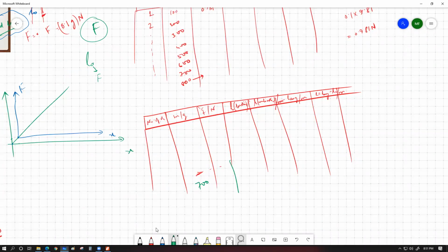So 700 gram is going to have one length value for the loading case and one value for the unloading case. Now you might wonder, within the elastic limit, these two lengths are supposed to be very much equal. This is absolutely true. For an ideal case, they are not supposed to be different, but in some specimens, in some experiments, they can prove to be different. If the applied force has somehow surpassed the elastic limit, then we're going to have different lengths over here.